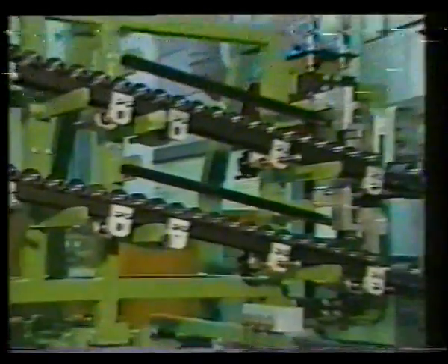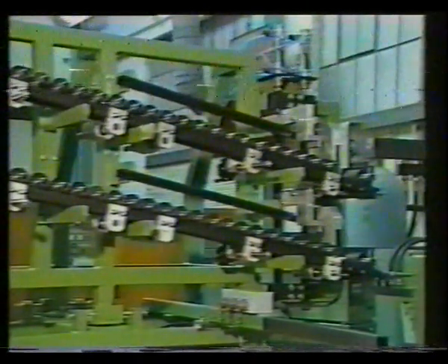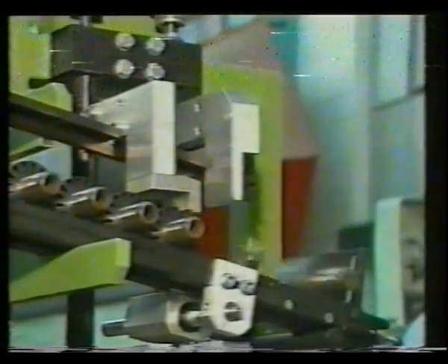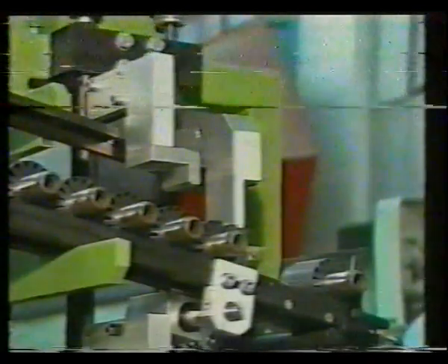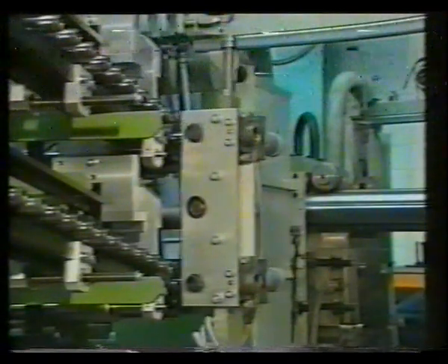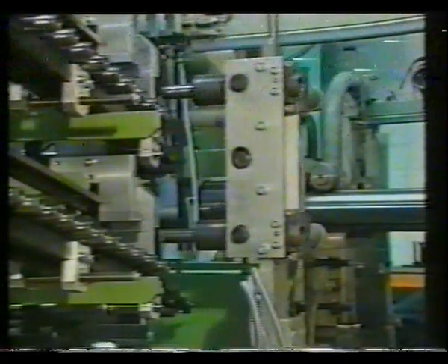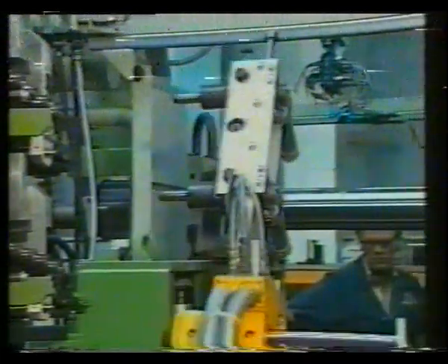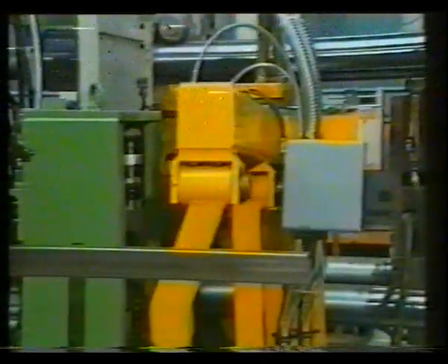The lamination stacks are manually loaded into the singling station. There they roll via flip-flop system to the bottom and the top loading stations. A limit switch signals the end position. A pick and place handling unit grips two stacks simultaneously and moves them vertically to the top end position. This position is identical for all the different rotor diameters.